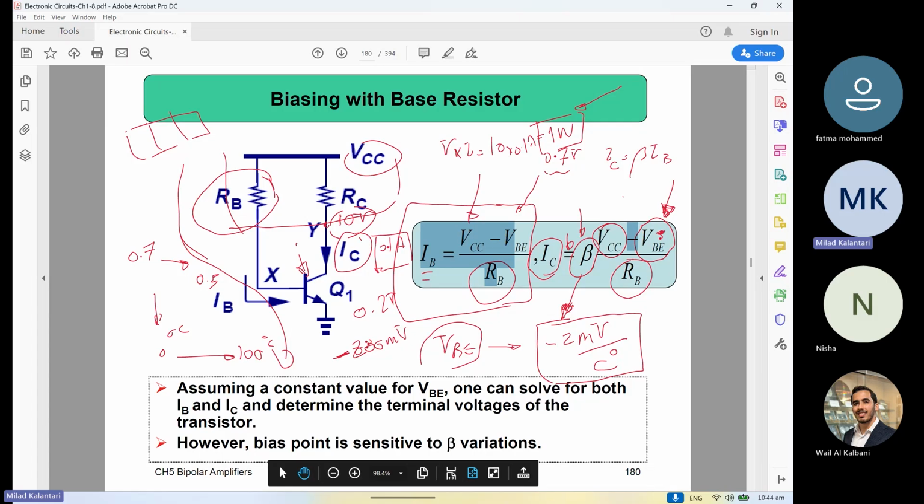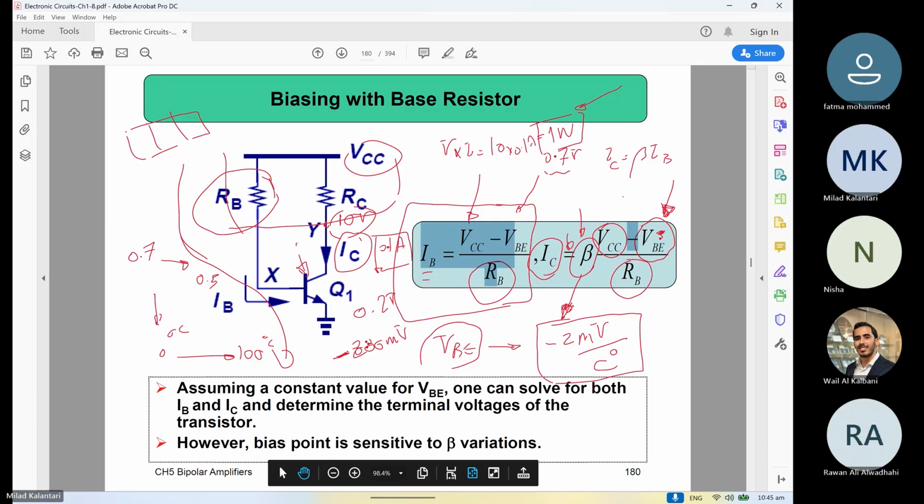And this loop will continue. It will be burned, right? If you do not control it very well, the device and the power dissipated into it keep going with a positive feedback, increasing the current until the device burns. And this situation, we call it thermal runaway for the device. So if everything is not well managed, then there is a chance the device goes to thermal runaway. Right? So the bias then is important.